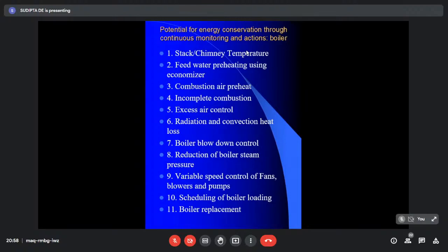Similarly, the flue gas going out of the boiler is also tested continuously with an online chemical flue gas analyzer, where the percentage of carbon monoxide is continuously and cautiously monitored, because if carbon monoxide increases, what does it mean? Incomplete combustion of carbon generates carbon monoxide, but complete combustion always converts it into carbon dioxide, and in that process you have a certain amount of heat release. So obviously the presence of carbon monoxide means incomplete combustion.